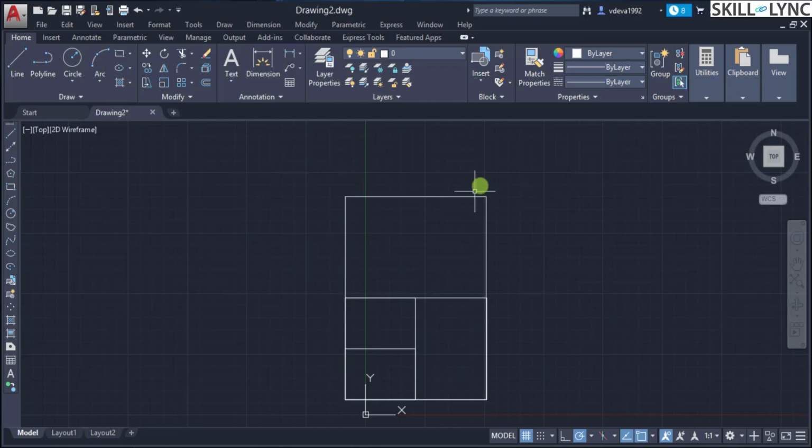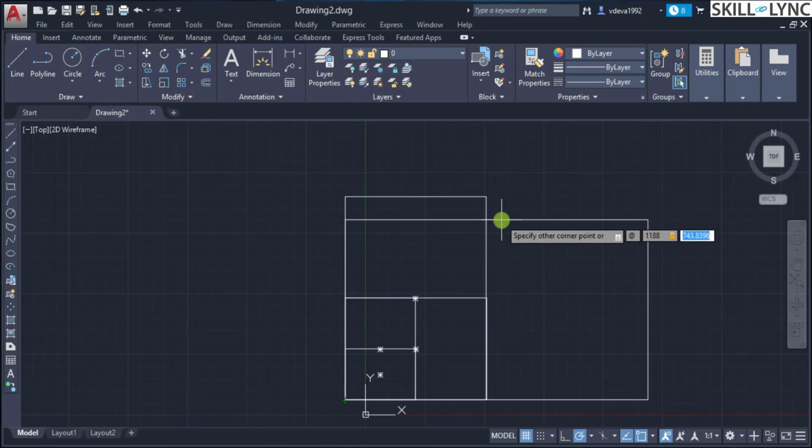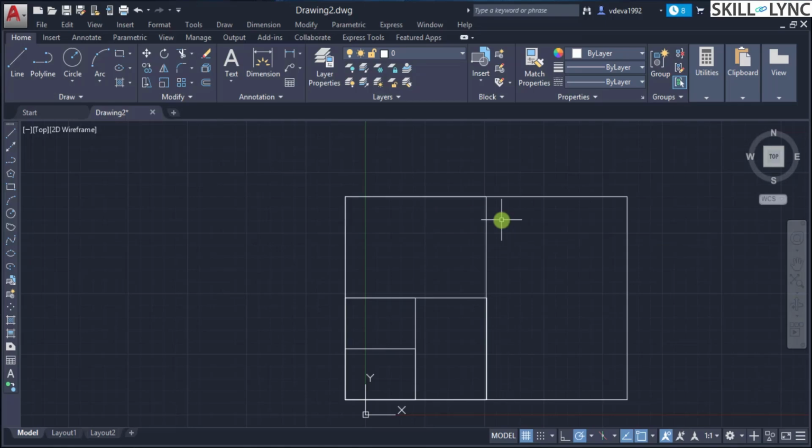And now let us unfold this A1 along with the width here to get the A0 size. So starting from this point, okay, and the next is multiplying the 594 width by twice, so we'll be getting 1188, and the height to be 840, the same as the A1. So this is how you have got the overall object. So now we can see the extents of it. So this extended area of this page is your A0 size.